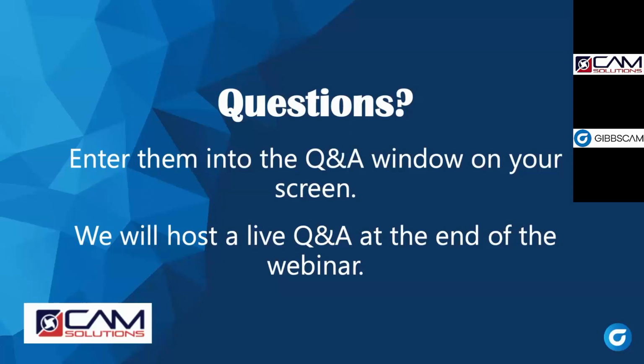Yes, you are correct. And there are plans to add new functionality to Gibbs Cam Probing. This again is the first iteration of Gibbs Cam Probing, and it covers basically datum setting, critical feature reporting, and with a very slight modification right now, your post will output cutter parameter update, and you can do dynamic remachining with the GoTo statement. So right there off the bat, we have 4 of those application protocols that are covered.